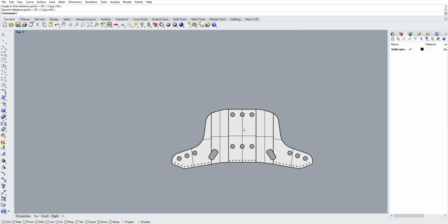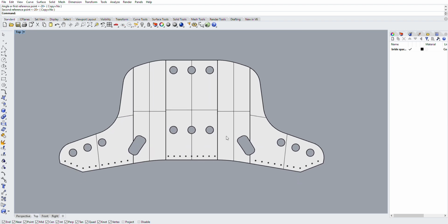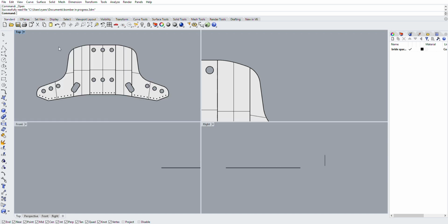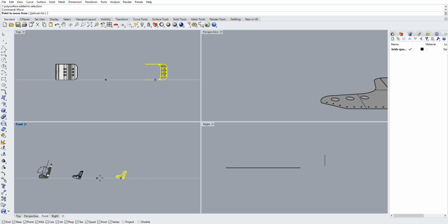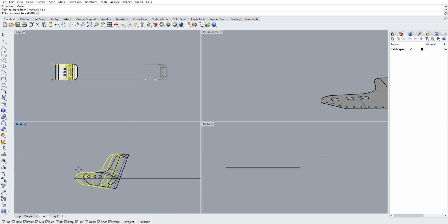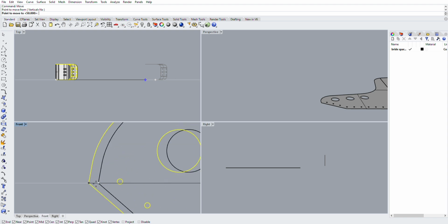Now, this is a super cool command because trying to build these with line tools is pretty much impossible. It gives me the advantage that I can work with curved shapes as long as it's on one plane. If it was a complex curve, a sphere, it would not unroll this shape. It would give me an error. But because there is only one bend in that plane on each side, the bends are in one dimension, I can actually just unroll it.